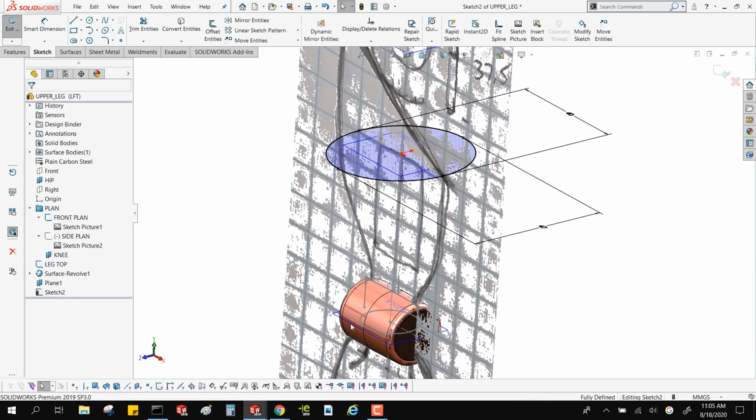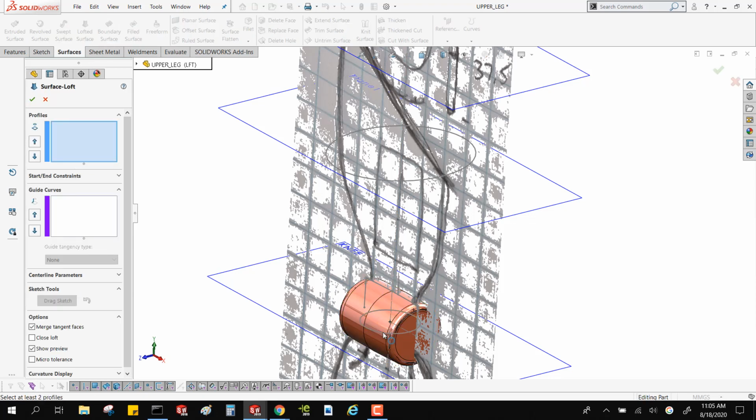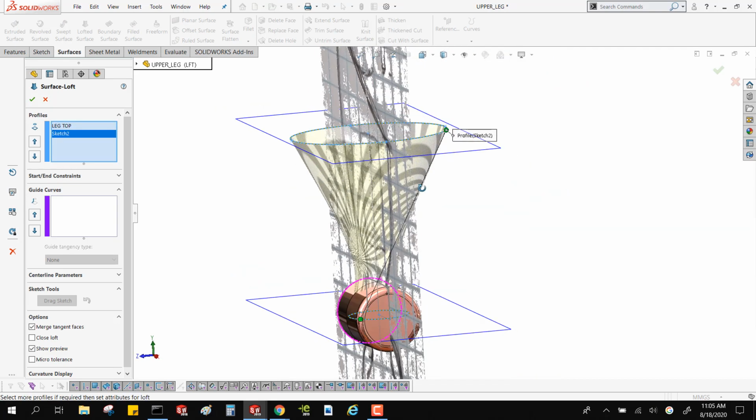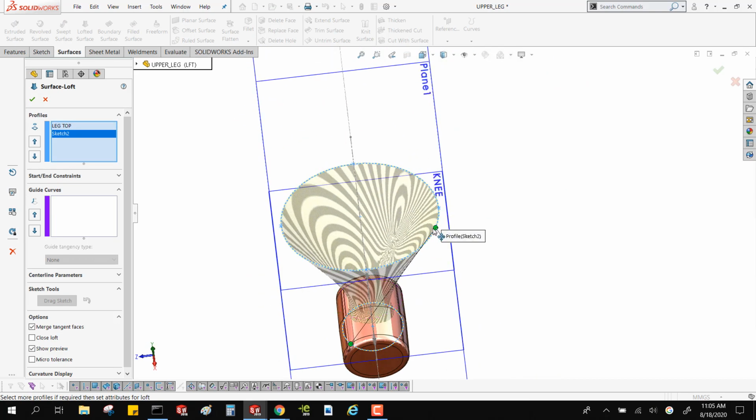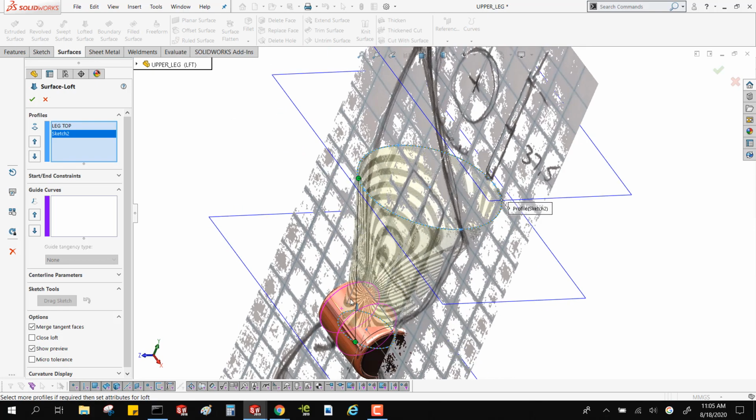I'm going to show this. I've got 2 sketches here. One is a circle, one is an ellipse. And so whenever you're dealing with this type of geometry that you're lofting from, you do want to be careful where you select. So when I am lofting like these 2 surfaces, it depends where I pick. See that little green dot? I can get this thing twisted up real easy.